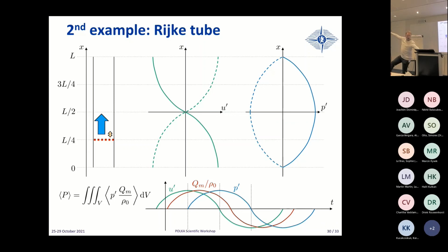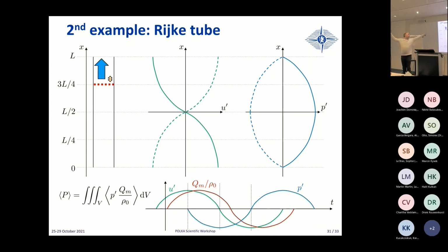Now, if you place the grid at another location that respects all conditions we have seen so far, non-zero pressure field, non-zero acoustic velocity field, you will see that it's not going to resonate because now this time, by the same argument, the heat transfer and the pressure are in phase opposition. So let me try to do this. First thing you will hear the difference of a wavelength. You will hear a detuning of the frequency because I will lengthen the resonator. You hear the frequency that is decreasing.